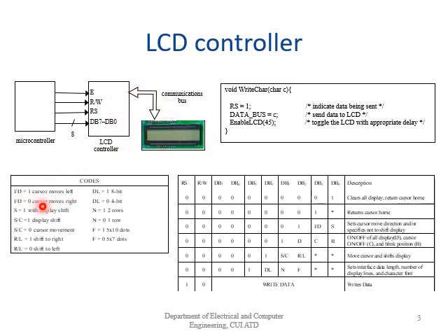So these are the codes. These codes will be used in this control word. For example, if you want to clear all display and return cursor to home, this is the data that we need to set. In RS we need to set 0. In RW, which is read write, we need to set 0. In all the data bits we need to set 0. However, DB0 we are setting 1. So once you set DB0 to be 1, it clears all display and returns the cursor to home.